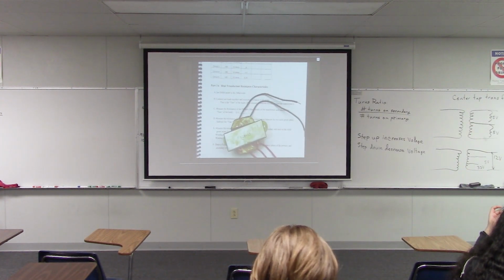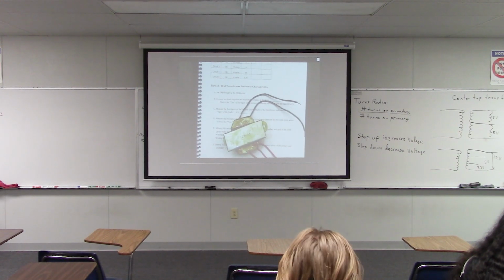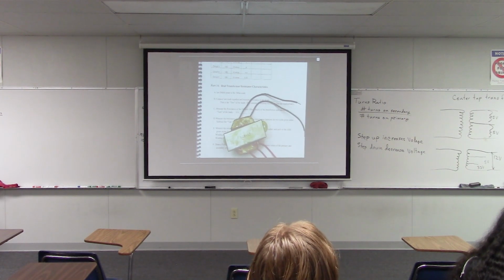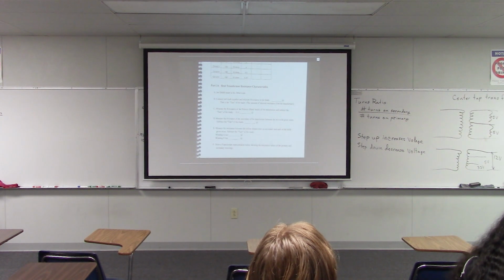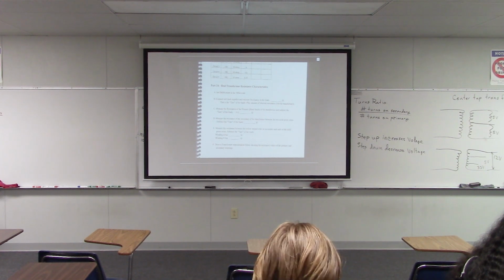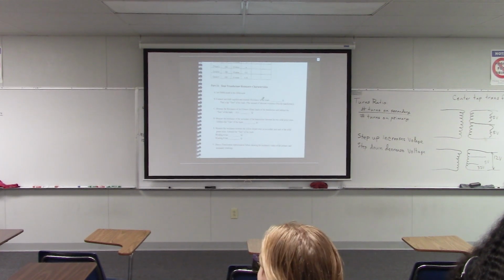And then, once you know that, you can subtract that from the resistance that you get when you connect the coil, and then that way you'll know that whatever's left over is just the resistance of the coil itself. Okay? So that's what the book is going to ask you to do.